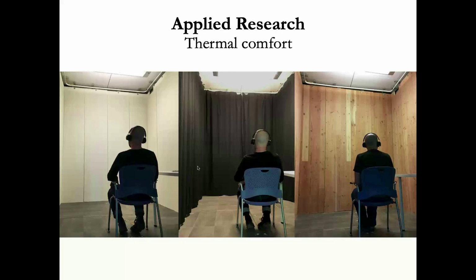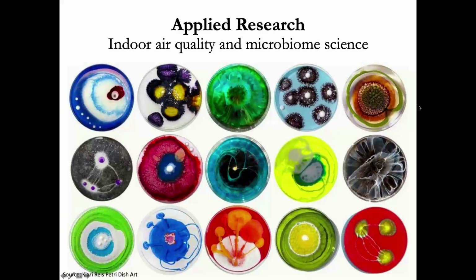What was interesting was that in the mass timber building, or this simulated mass timber building that we created, occupants were willing to experience a wider range of temperature variations, either cold or warm, without feeling uncomfortable. So that has implications for the overall heating and cooling requirements of these kinds of buildings versus something that's done in concrete, for example.